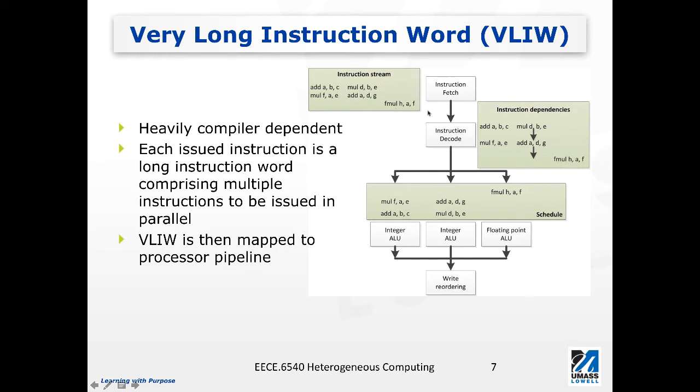So these instruction streams go through the same instruction fetch stage, while at the decoding stage, these instructions will be decoded. But keep in mind, in this case, because we're using very long instruction word, there's really no need for the hardware to maintain a very complex logic to analyze the dependencies, because we assume all these dependencies have been resolved at the compilation stage.